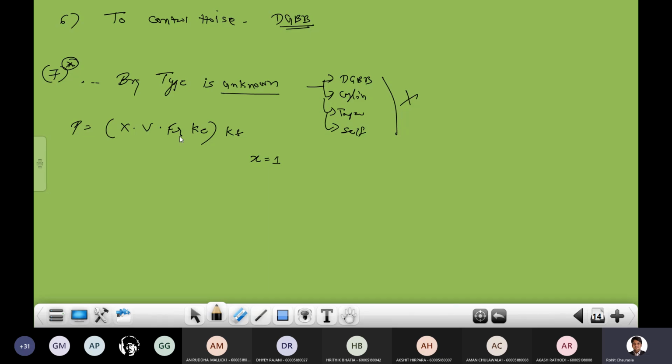Once I define the particular bearing, वो particular bearing को define करने के बाद I will apply that previous वाला formula. एक मुझे आइडिया आ जाएगा कि here deep groove ball bearing may be suitable, cylindrical will be suitable, taper will be suitable. Once I get the type of the bearing, then I will apply that previous वाला formula, P is equal to XV Fr plus Y Fa into Ks Kt. वो वाला formula apply करूँगा, once we confirm the type of the bearing. If this type of the bearing is unknown,